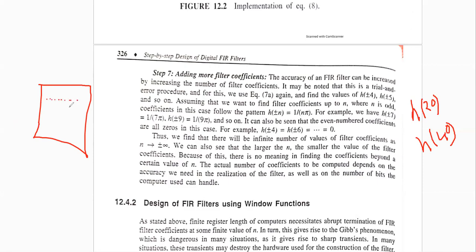You do the convolution sum with your xn, and you need some mathematical calculation, and there are a lot of multiplications and additions. If you improve the order of the filter, or add some coefficients, then the multiplications and additions will also increase.